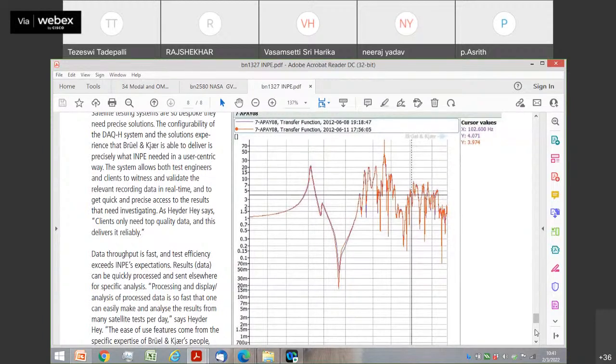After doing the test, we checked through the signal conditioning also, and we checked after also, the sensor was okay. But the data was for 20 seconds or 60 seconds. Initially 20-30 seconds of data was okay, and after also okay, but in between there was data on one side only. I would look at 2 or 3 accelerometers mounted in different places in the structure and see whether it is a sensor problem or a cabling problem.